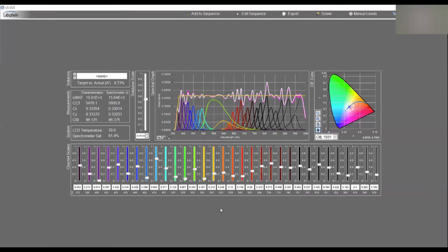The system has a built-in NIST-traceable spectral radiance calibration tied to a tungsten halogen source, which is in the source, and this spectroradiometer, which is calibrated for spectral radiance responsivity, and you have the feature to recalibrate that spectroradiometer anytime. When you run the recharacterization, it uses that spectroradiometer to re-optimize this system over its full dynamic range.